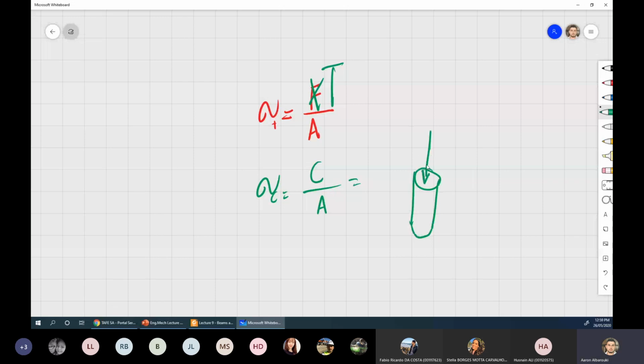They found the maximum force they applied divided by the area of that cylinder of concrete, and they got the number 32 MPa, which is Newton per millimeter square. So they found the force in Newtons and the area in millimeter square, and the maximum force they could apply before it broke